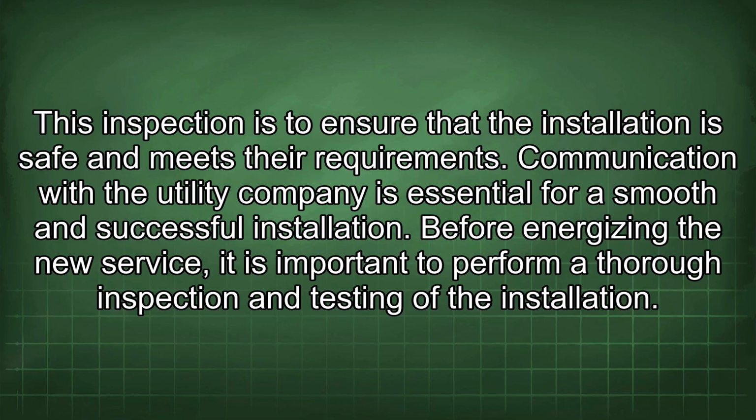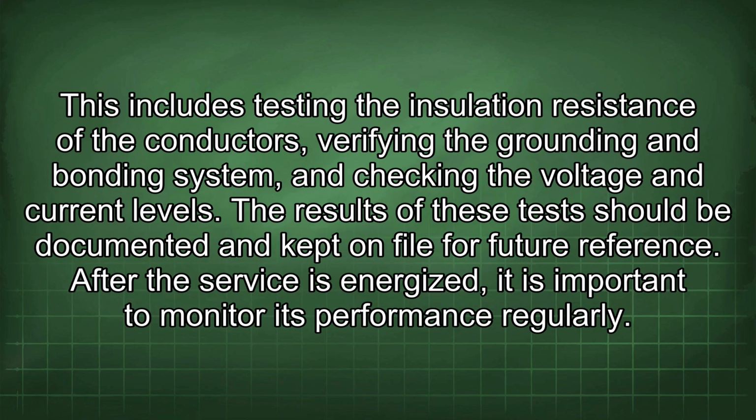Before energizing the new service, it is important to perform a thorough inspection and testing of the installation. This includes testing the insulation resistance of the conductors, verifying the grounding and bonding system, and checking the voltage and current levels. The results of these tests should be documented and kept on file for future reference.